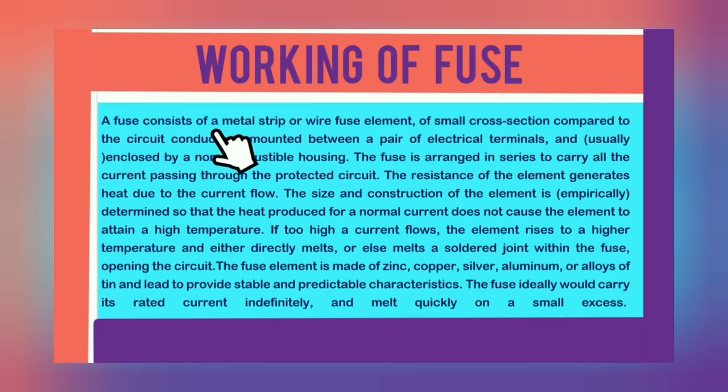A fuse consists of a metal strip or wire fuse element of small cross section compared to the circuit conductors, mounted between a pair of electrical terminals and enclosed by a non-combustible housing. The fuse is arranged in series to carry all the current passing through the protected circuit. The resistance of the element generates heat due to the current flow. The size and construction of the element is determined so that the heat produced for normal current does not cause the element to attain a high temperature.